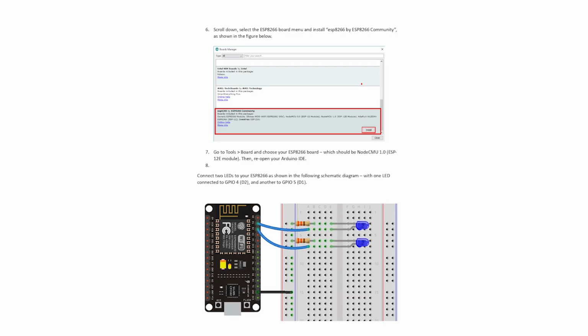So, make these connections and connect the ground of this board to the ground of the breadboard. That completes the circuit. Your power is coming in here, and then you have one LED and then the resistor and the ground. And in parallel you have another LED and another resistor with the ground. Everyone understands the circuit? It is a simple circuit.